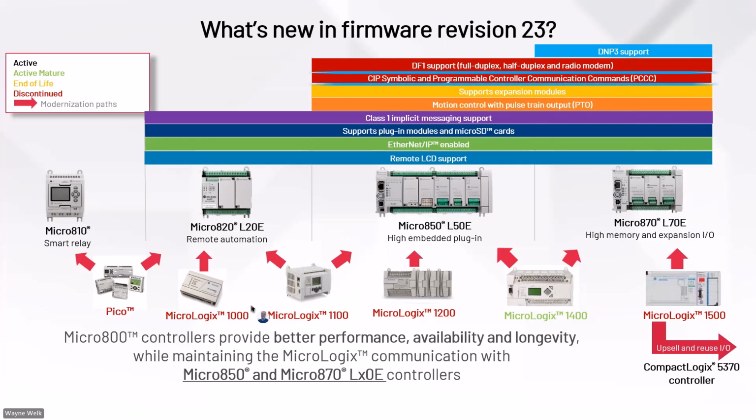Generally, if it's a 1400 or a 1500, you're going to migrate to CompactLogix, but the smaller platforms where you have the MicroLogix 1000, 1100, and 1200, those fit more of the model of the Micro850 and Micro870 on the migrations.